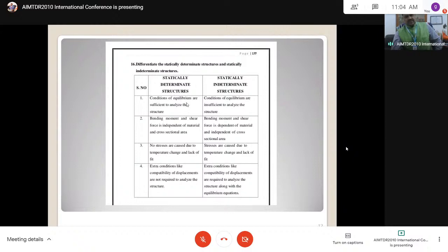Let us take a simply supported beam, one end roller, another end hinge. An external load is applied. The hinge allows only rotation, something like this. The roller is something like, if I can consider, this is the roller. Rotation as well as translation. The unknown is the vertical reaction. The hinge allows only rotation, with the two translations, x and y restrained.